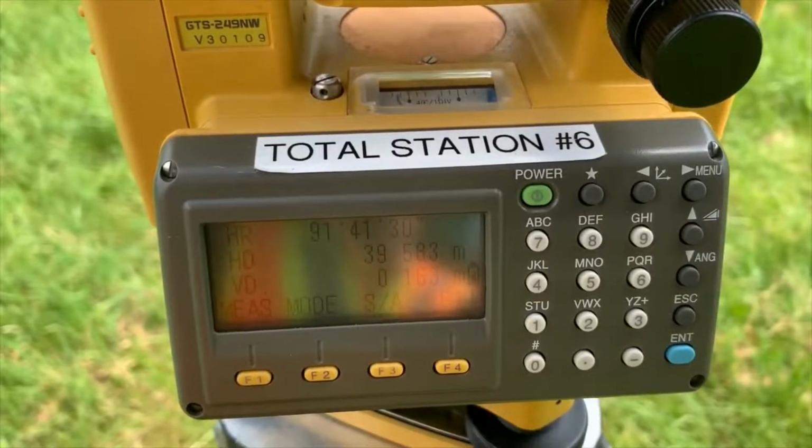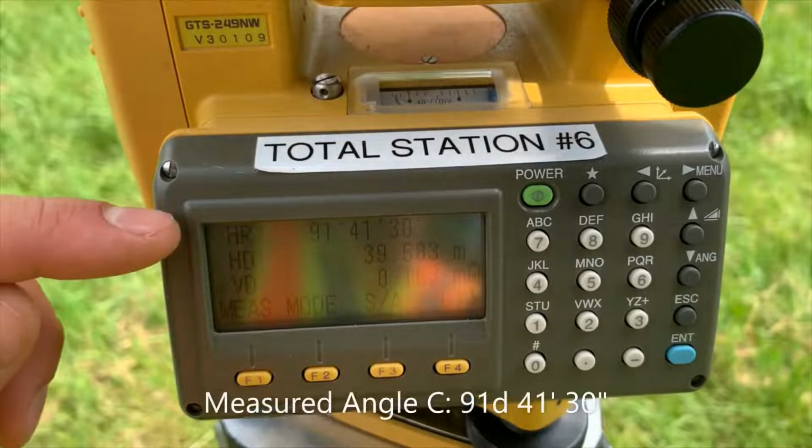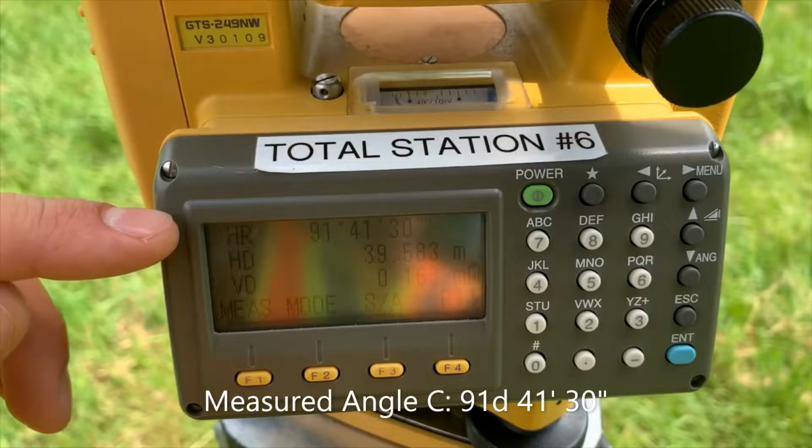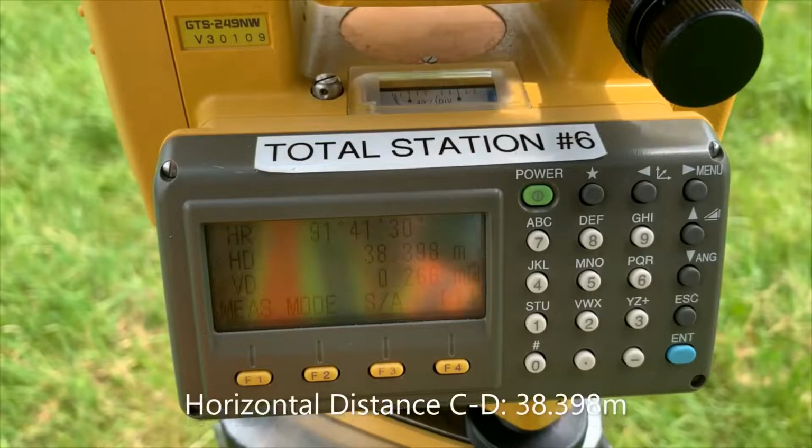So now we've rotated our total station and sighted on a prism on D6. We can see our horizontal rotation is 91 degrees, 41 minutes, 30 seconds. And we'll take a horizontal distance reading, which is 38.398 meters.